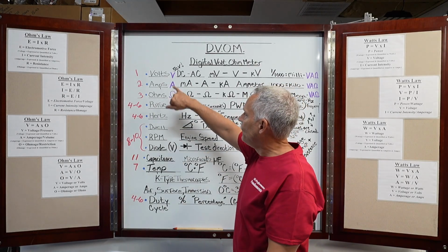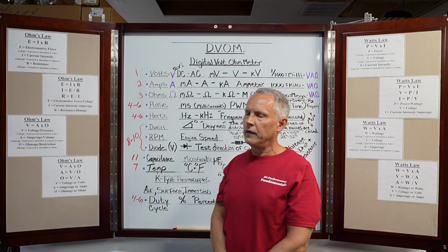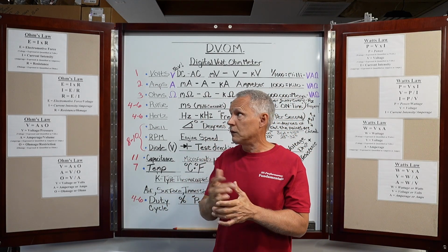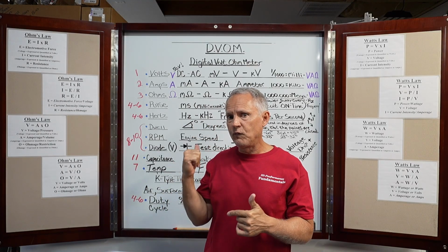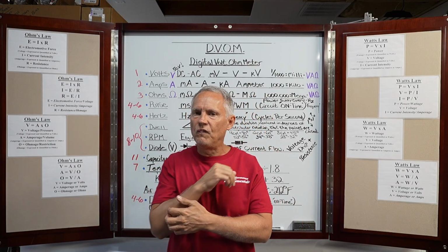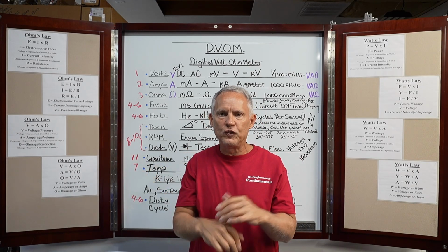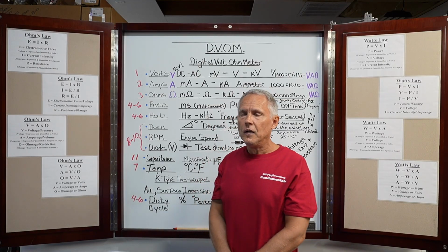Well, at about 50 volts DC, you need to start thinking about it. For example, let's say you're working on a 48 volt system. Well, that's less than 50, so you're good. Well, when the car's running and it's charging that 48 volt battery, it's going to be between 54 and 58 volts. Somewhere in that area, certain applications may differ. But let's say 54 to 58 volts. That's definitely more than 50, right?